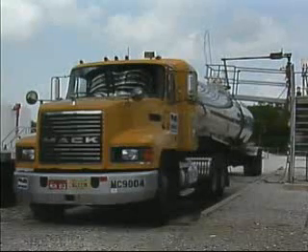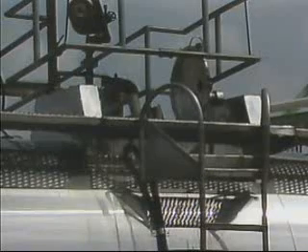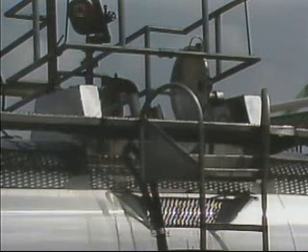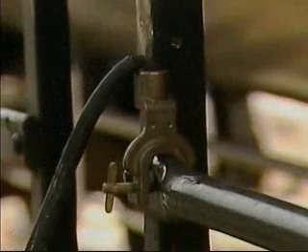The buildup of static electricity increases the chances of sparking. If sparking occurs near a tank's manway, where a mix of air and vapor may exist, a fire and explosion hazard is created. A common way to deal with static electricity is to use a grounding cable. A grounding cable draws off electricity to ground.